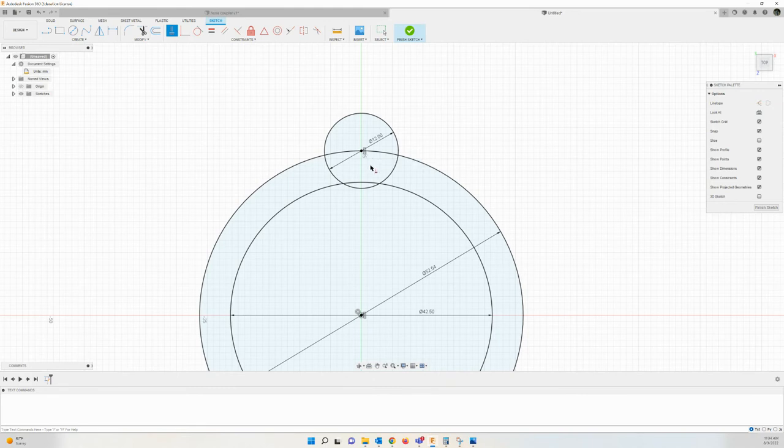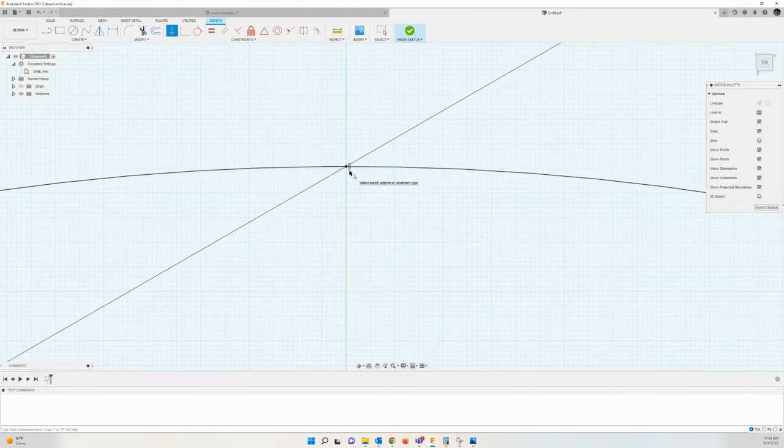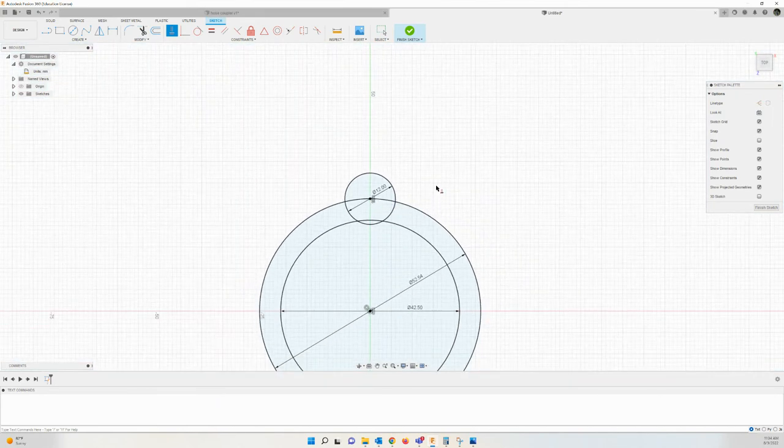Notice I get constraint, and if I zoom in now, it's been moved to where now it's on the green line, on that axis. I'm going to escape out of the constraint tool, but it's also giving me these symbols showing that the constraint exists. You do not have a constraint if those symbols don't exist. And as you look at your constraints up here, the various ones, those are all the symbols that would be associated with it.